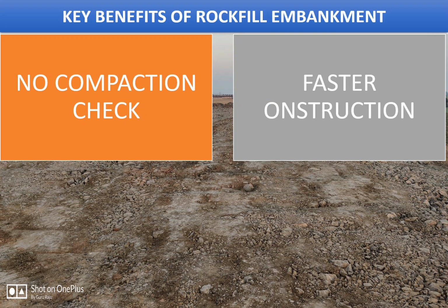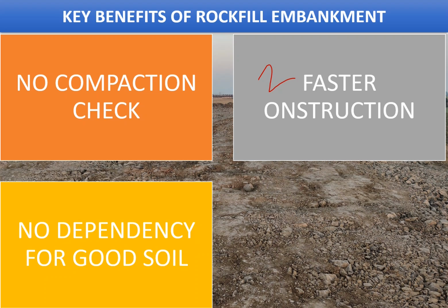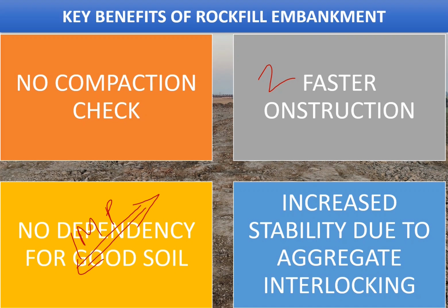Faster mode of construction is a second benefit, and then you have no dependency on the search of the good soil. This is the most important aspect as far as the project is concerned. Otherwise, because of the requirement of the availability of good soils, you lose time and spend more money on materials from a longer distance, a longer lead, and then increased stability due to aggregates interlocking.